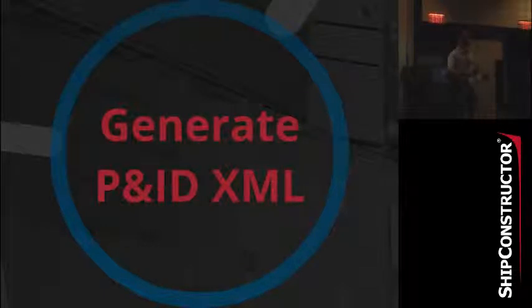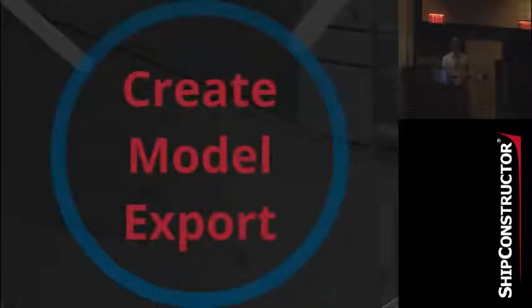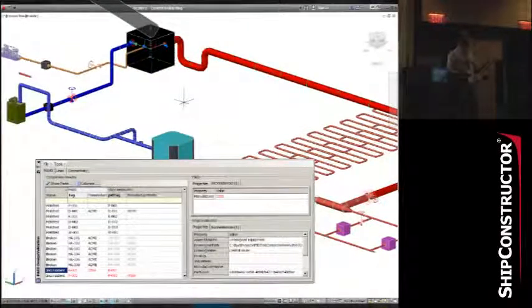So what's the process? You kind of probably already got it from what I've just said, but let's talk about it. Start with your P&ID diagram. That's all designed. You've got all of your information in there, your knowledge, if you will. You generate your P&ID XML. Now, this can be done by a lower-level user who's just been handed the P&ID DWG, or it can be your actual senior designer, whatever you like. You import your mapping rules, and then you create your model export. Simple as that, and then you get your results.